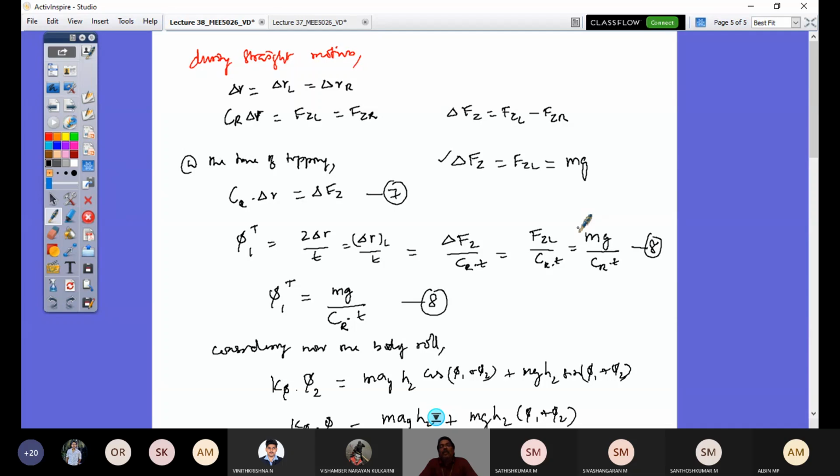And then to study our critical lateral dynamics, from a stability point of view, what would be my optimum design of suspension? I require to calculate two rolls: the roll of axle and the roll of body and the threshold values, and that helps us find out the threshold limiting value of lateral acceleration, the maximum value of lateral acceleration permissible just before the rollover of your vehicle, right? So this is all sufficient in this part,